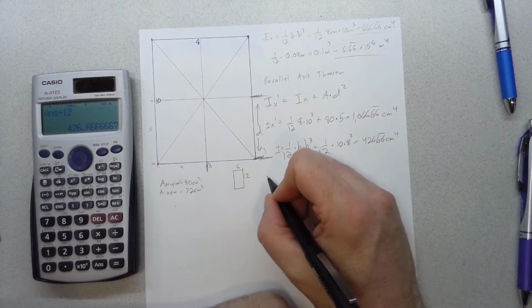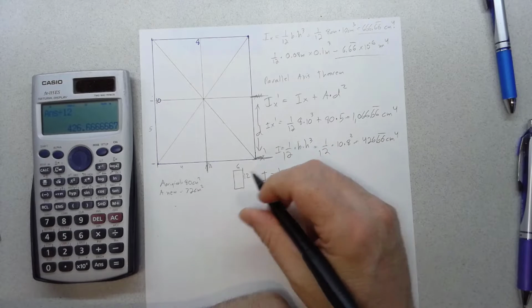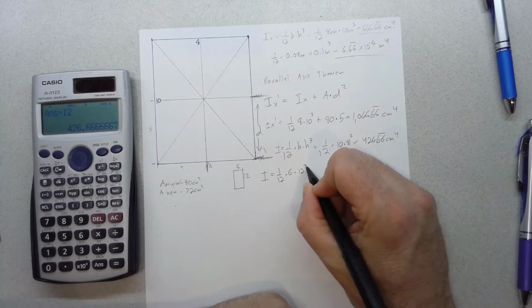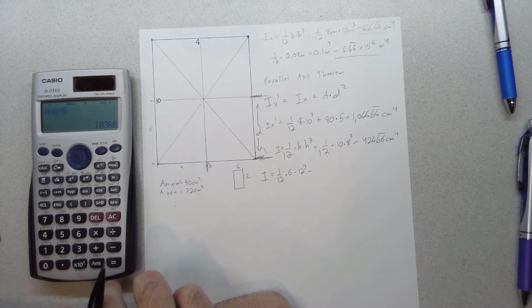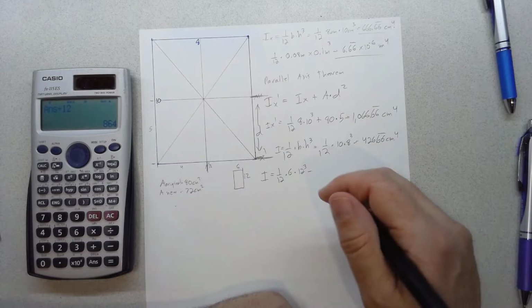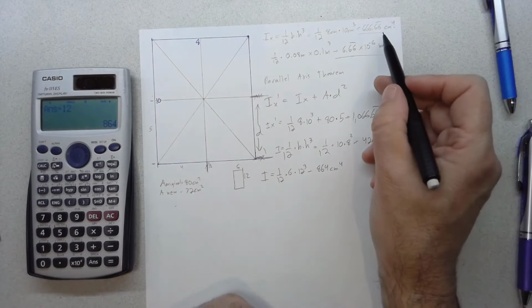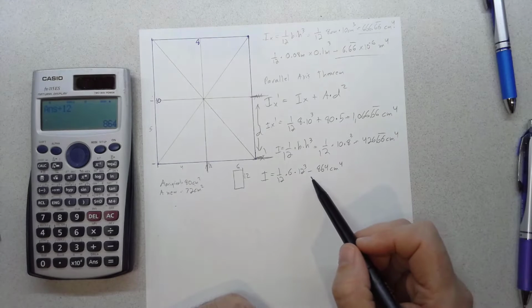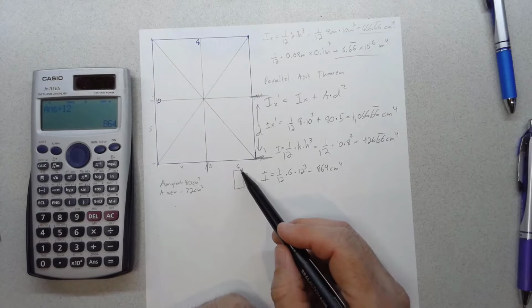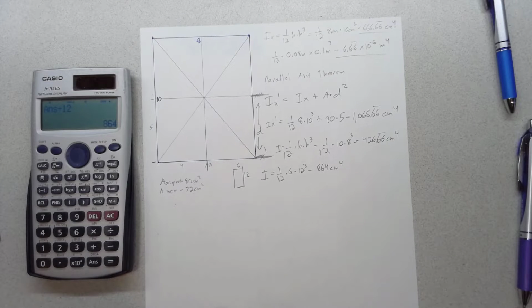And let's look at what happens to I, its stiffness about bending. So I is going to be equal to 1/12 times the base. Our new base is 6 times 12 cubed. So 12 cubed times 6 divided by 12. And the answer is 864 centimeters to the fourth. So our original was 666 centimeters to the fourth, and that used 80 centimeters squared of material. By readjusting the dimensions of our beam, we went to 72 centimeters squared of material, and we got a stiffer beam. So that's why, again, just kind of trying to think ahead to why engineering shapes are the way they are.